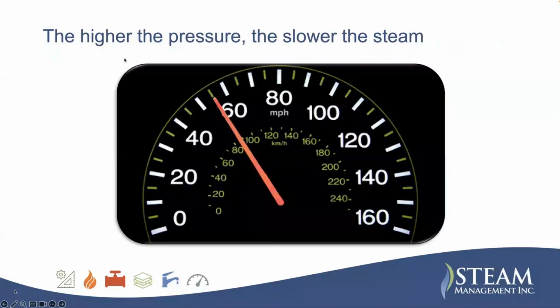The higher the pressure, the slower the steam, right? It goes against everything we're saying. We want steam to get there faster. You think, well, I'm going to increase that steam pressure. All that does is slow it down.